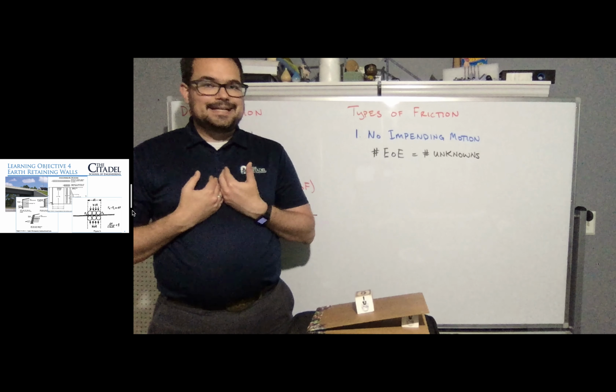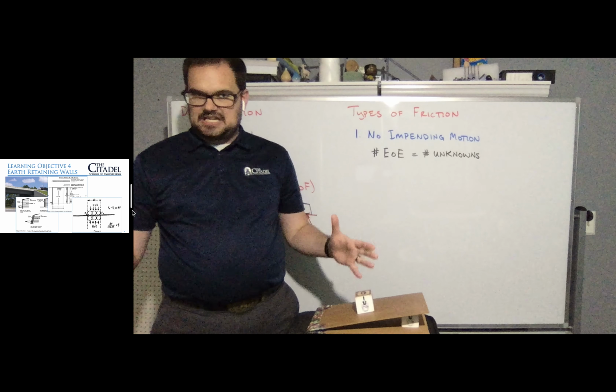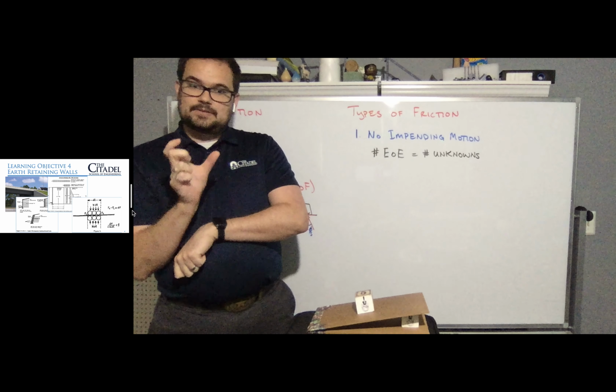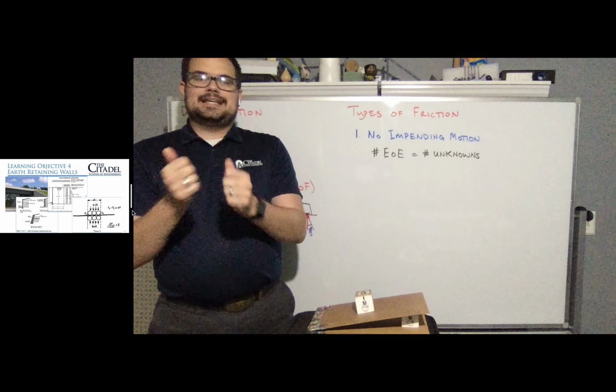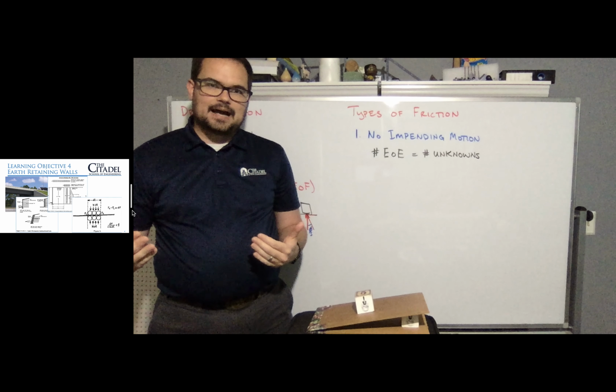As opposed to me, I rarely corner in the family minivan doing 100 miles an hour. Like, it just doesn't happen. And so the tires on my minivan have tall sidewalls and relatively narrow tread, so that the heat will actually dissipate out the sidewalls and increase the lifespan of my tires.